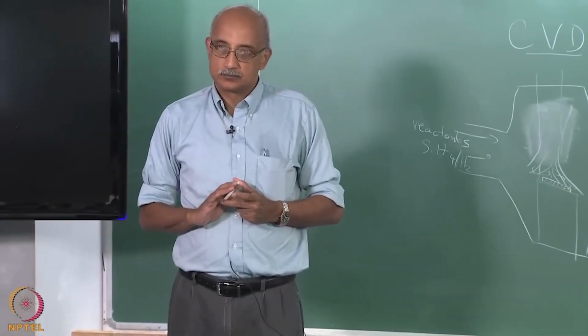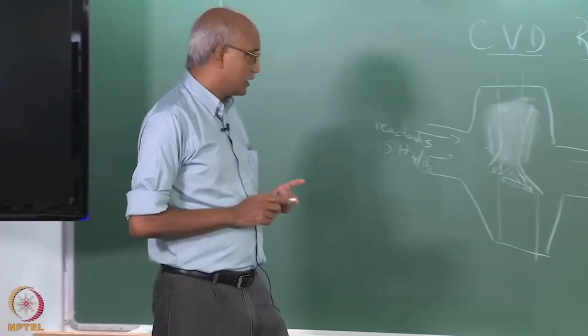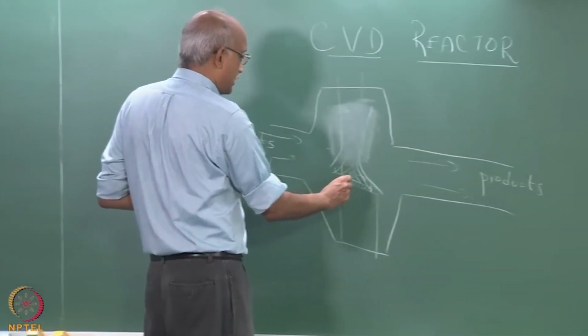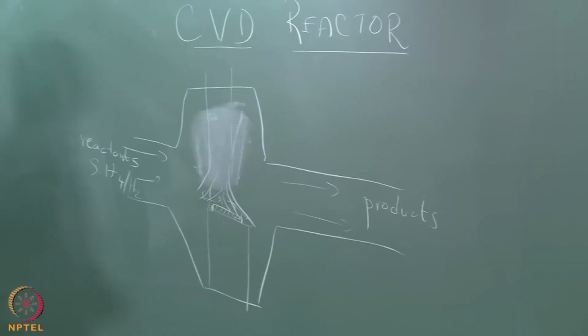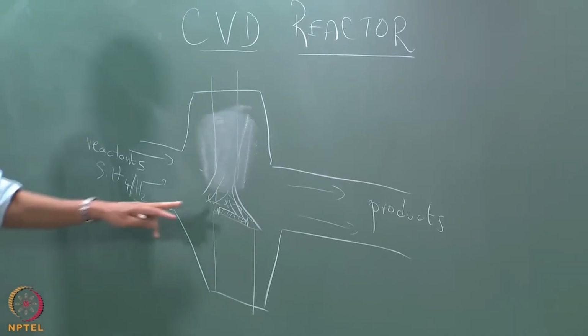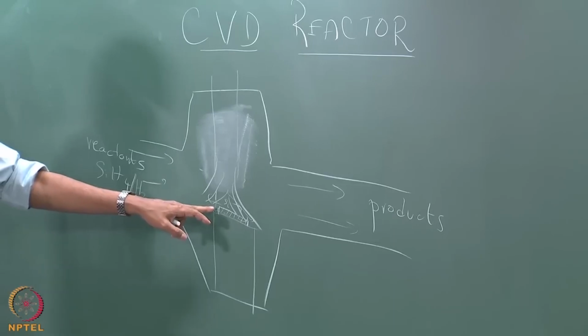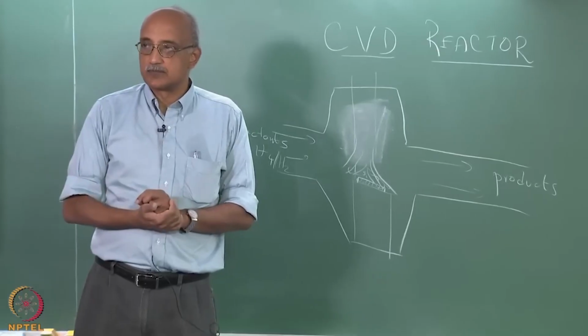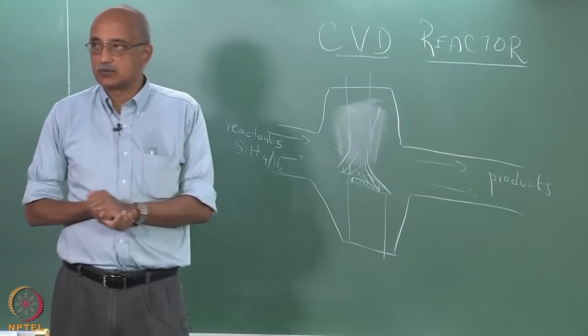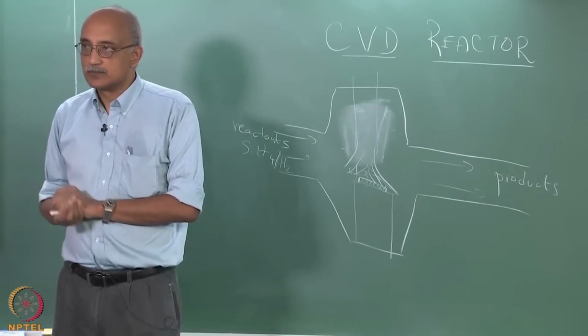On the sides there may be the formation of deposits. That is not a big issue, that is not a critical functional area of your substrate, and again I think that can be minimized. But as far as the front, the deposition surface, will you get a more uniform substrate with vertical stagnation flow?